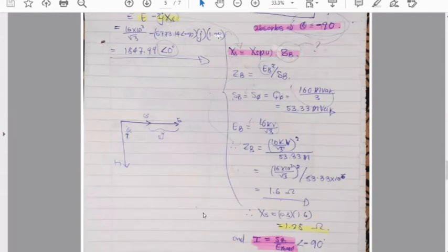But we need XS first. In order to calculate the synchronous reactance, you multiply what is given to you in per unit by the impedance. In order to calculate impedance, you need your voltage, which is given to us, and you need your power, S. But this S is given to us in three phase, so we're just making it into per phase. And then you can simply substitute this value into this equation.